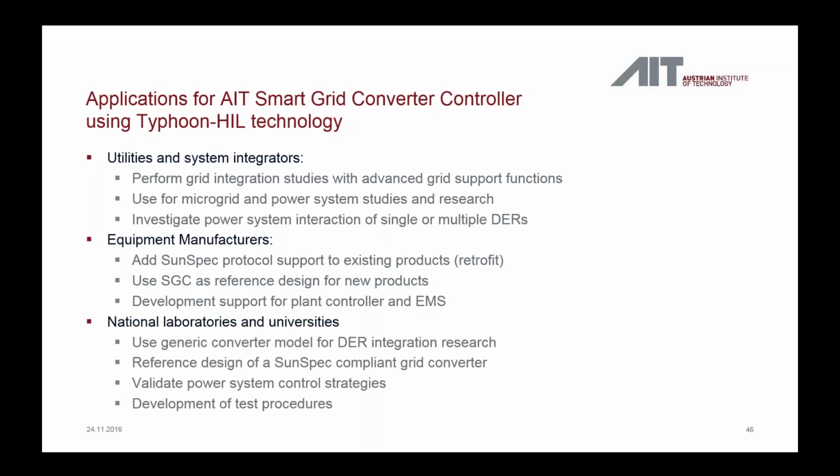Last but not least, also for the research world, it can be very useful as a generic converter model for DER integration research. It's a reference design of a Sunspec compliant grid converter, which can be used, for example, to validate power system control strategies, and also to develop test procedures. So for the last application, the AIT Smart Grid Converter is already being used by Sandia National Laboratories in the United States to support their development of automated test procedures and test scripts to validate the compliance of inverters.